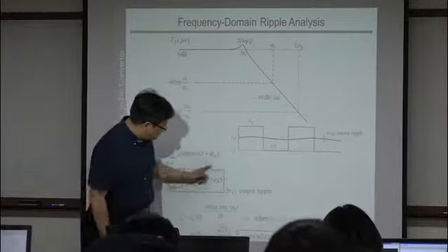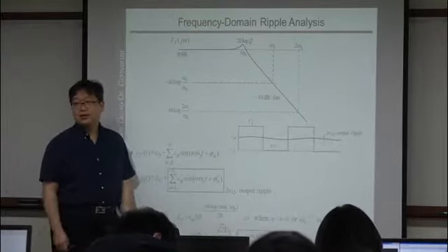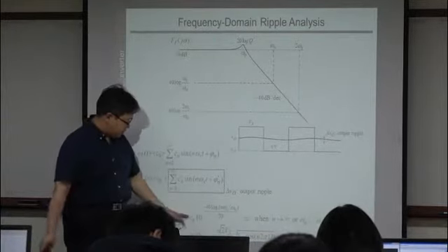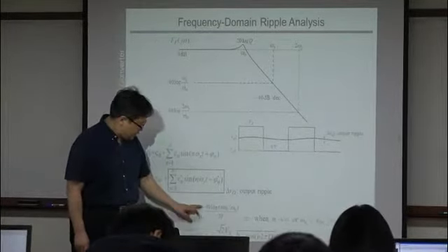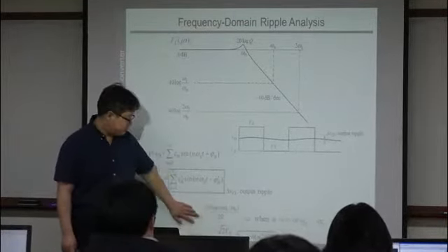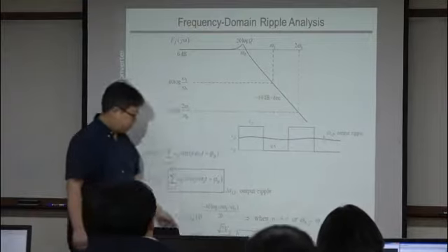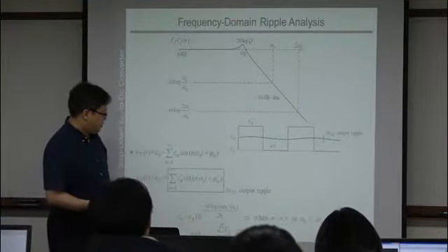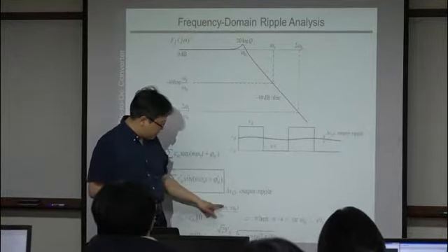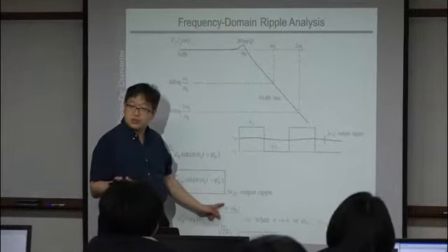So this equation models the reduced effect by passing through the low pass filter, okay? Your Cn dash is simply calculated as 10 to the minus the Bode magnitude at n omega s over omega 0, over 20. This magnitude is this magnitude, right? At the switching frequency, n is selected as 1, and at double the switching frequency, n is selected as 2, okay?